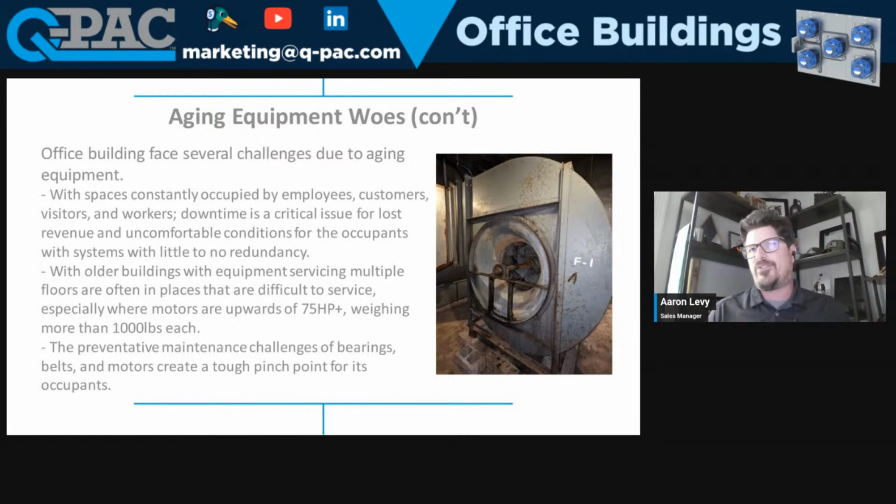And what they face with these challenges is that a lot of these occupants are in the building most of the business day, and the only time they really ever have downtime is either in the evenings or on the weekends. So a Q-PAC system can be installed normally, depending on the size of it, in less than 8 hours after demo. So normally they'll shut down Friday night, start demoing it, be ready to install it on Saturday evening, and then by Sunday morning they're up and running, ready for the occupants to come in on Monday, none the wiser that equipment's been serviced.